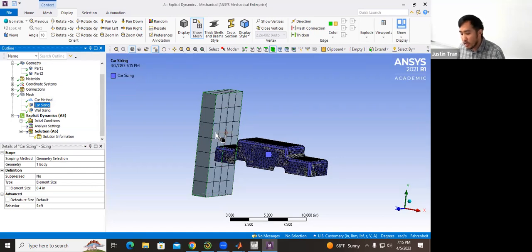And actually, I'm looking at the activity specifications. I do say that you can do a mesh convergence test, but it is extra credit. So if you do a mesh convergence test for this one, it is extra. Just be careful because each dynamic simulation, especially as you refine the mesh, is going to be really expensive. So I would recommend doing the mesh convergence test if you have a lot of time on your hands, or maybe you're watching Netflix or something, just run a simulation every half hour or so, and get data that way.